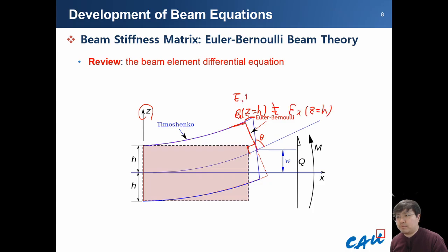This is Euler beam theory, and this is Timoshenko beam theory. So they will show a slightly different result. I'm not sure that Professor Yang taught you about Timoshenko beam theory. However, Euler beam theory is enough to understand the concepts of the FEM method in the beam element. The only difference is that they added some angle distribution behavior, so they added one more very simple theory.